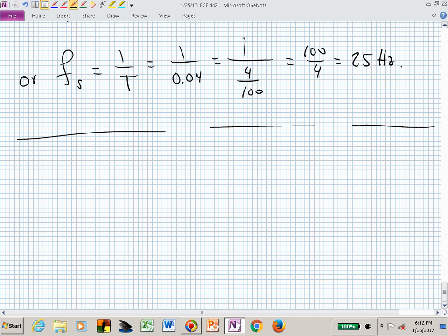So we're now finding the discrete equivalent to some S domain expression or relationship. But typically we'll just say S to Z for now, until we get to that section of the class. But it's a discrete equivalent. We're simply moving from the continuous time into the discrete time in the frequency domain.